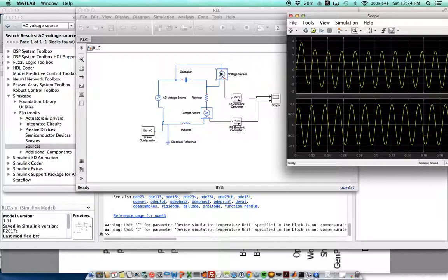So you can move this voltmeter around, right, to the different components. Just make sure that your positive side is on the high side of each of the components, and your negative side is on the low side. So the high side is towards the battery or towards your voltage source, and the low side is towards ground.